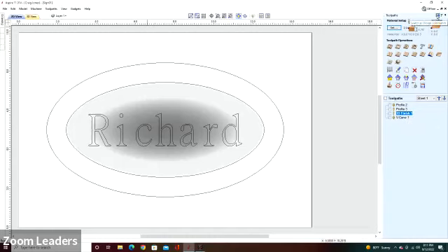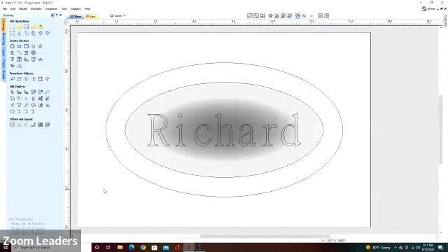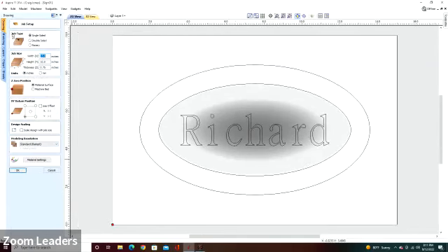So fairly quickly, and I'm not controlling this very tightly, set of tools. You've got certain file operations. You can go in and set up your X, Y, and Z. So up here, it says, okay, the width of this particular material, the height of the material, and the thickness of the material, those are important to know, because if you're going to carve down toward the bottom.